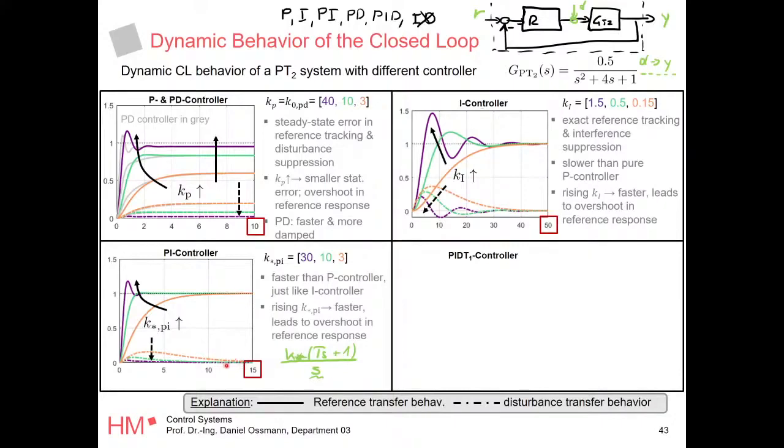Now we are fully accurate, again, like in the integral case. Also for the disturbance, so they get to 0. I just didn't want to increase the size here. And we are faster again, right? So we are in the time scale of 15 seconds now. So we are accurate and we are fast, right? So, okay, you could argue, well, we are still not in that time range here. Still, the integrator does you some harm here. It makes you pretty accurate, but still it's not perfectly fast.